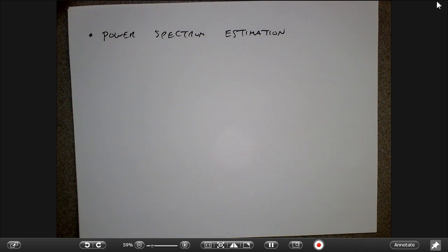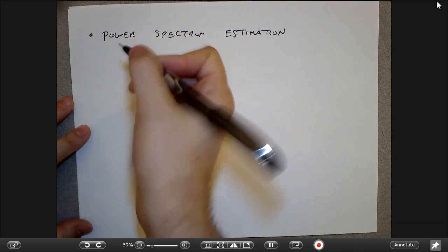So it's a way of getting frequency analysis from the signal without doing a full-on FFT. It's a different route, and it gives a coarser or smoother frequency analysis than you get with the FFT. Some of you are using it in your projects to get the basic peaks in the frequency domain without taking a full FFT. There are different ways of doing this, and that's at the back of the book.